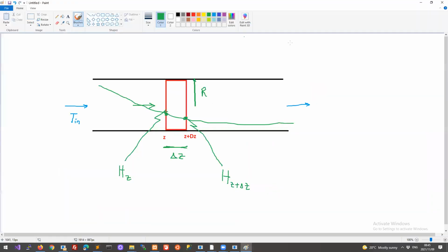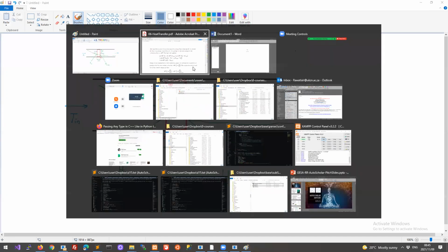And now we are also concerned about the flux due to conduction. On top of the fluid just flowing around, you also get conduction through the fluid. So energy is being transferred due to conduction at a certain flux. A certain flux is arriving into our controlled surface, and we have to multiply by that surface area, and it's leaving the surface, and we also multiply by that surface area.